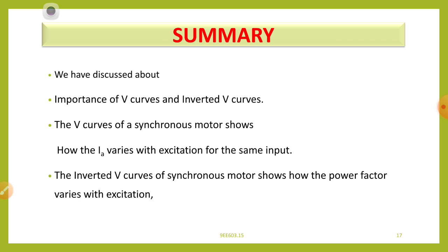Based on this performance, we maintain synchronous motors in our industries to improve the power factor of the industry, where nearly 70% of the motors available for different applications are induction motors, which always draw lagging power factor.